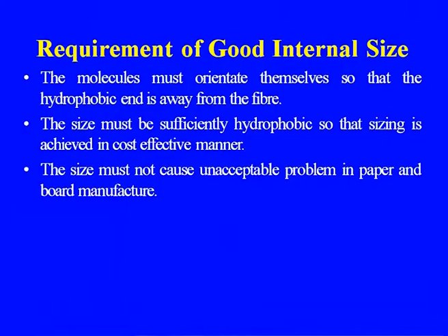The molecules must orient themselves so that the hydrophobic end is away from the fiber. The size must be sufficiently hydrophobic so that sizing is achieved in a cost effective manner. The size must not cause unacceptable problems in paper and board manufacture. These are some of the requirements of a good sizing.